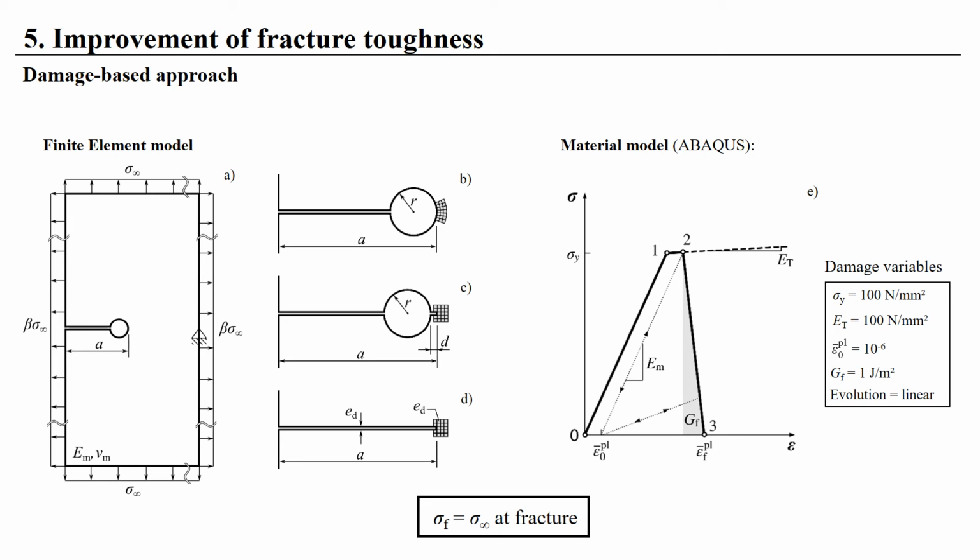For the case with defect, a worst-case scenario is assumed for the position of the defect. The defect is located at the boundary of the hole and oriented in horizontal direction. Figure D represents the reference configuration of a crack in the homogeneous material. The crack in the reference configuration as well as the defect at the hole are modeled as a rectangular notch